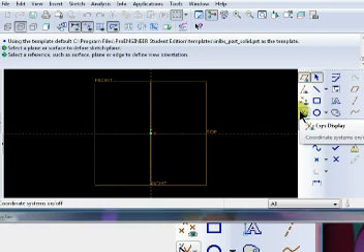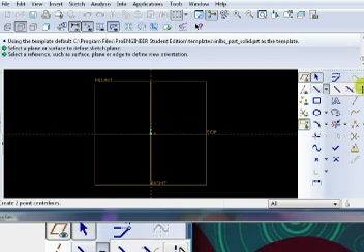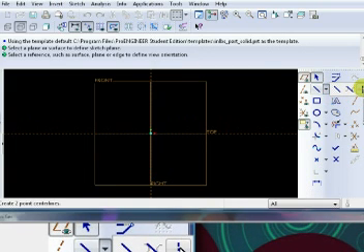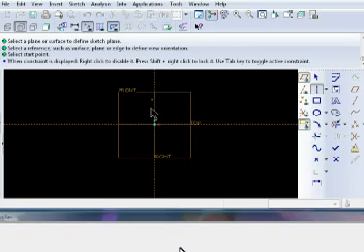Every time you're about to create a Revolve feature, you will need a center line. That center line becomes the axis of revolution. So make it a habit to start with the center line before you even draw any other geometry. Now to define a center line, you need two left mouse clicks, and in this case it lies right on the right datum plane, so one click, two.